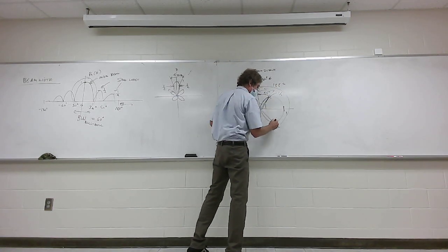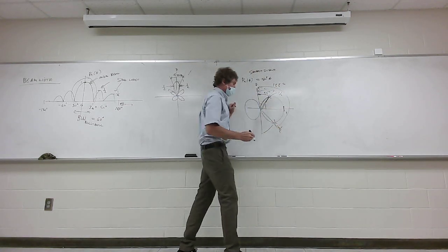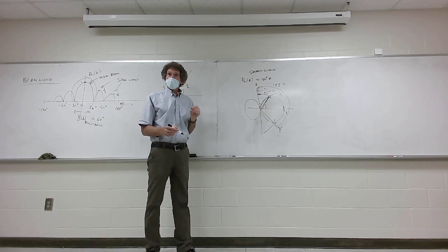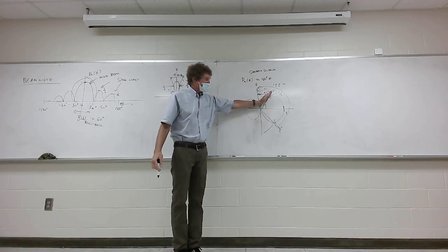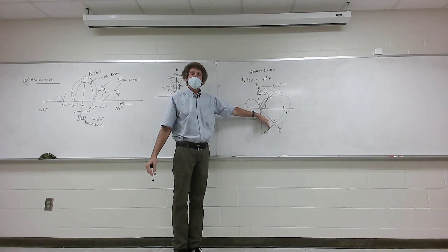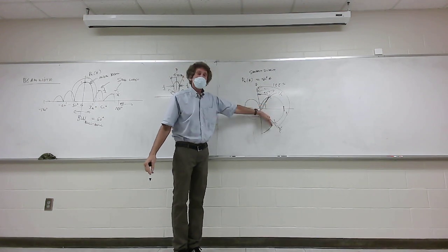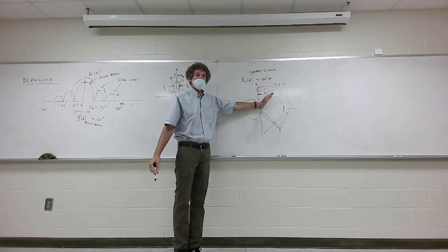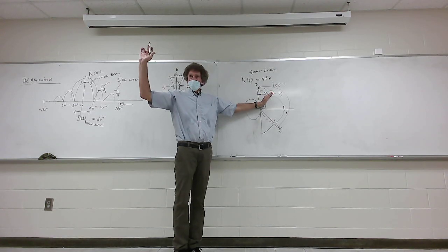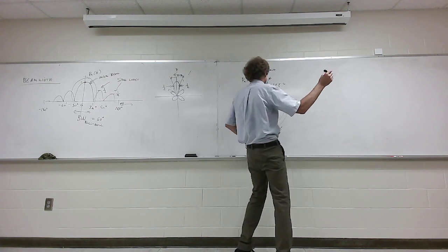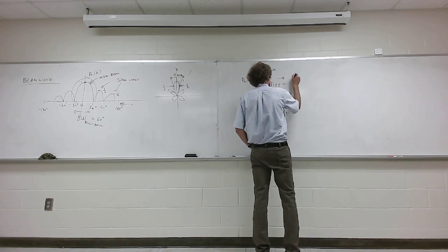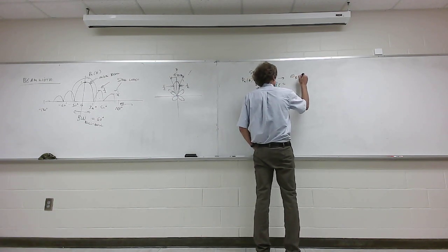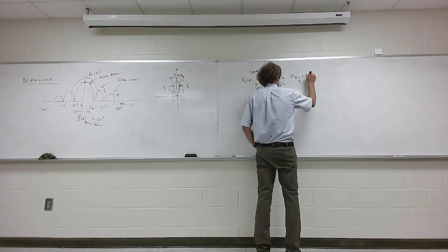And this would be 1/2. Y'all follow me? So what's the angle between this point and this point? Just look at it. Well, it would be 135 minus 45, or 90, wouldn't it, class? How many see that? And that's horrendous as far as gain. So that means this has a half power beam width equal to 90 degrees.